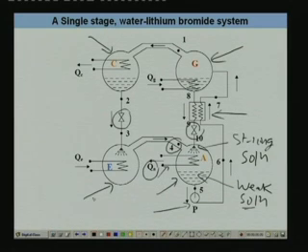This weak solution is at low pressure, and it is pumped using this solution pump. The solution pump increases the pressure of the solution, and this high pressure solution now flows through the solution heat exchanger here, where it exchanges heat with the hot solution coming from the generator, and it becomes heated up, and this hot weak solution enters into the generator.